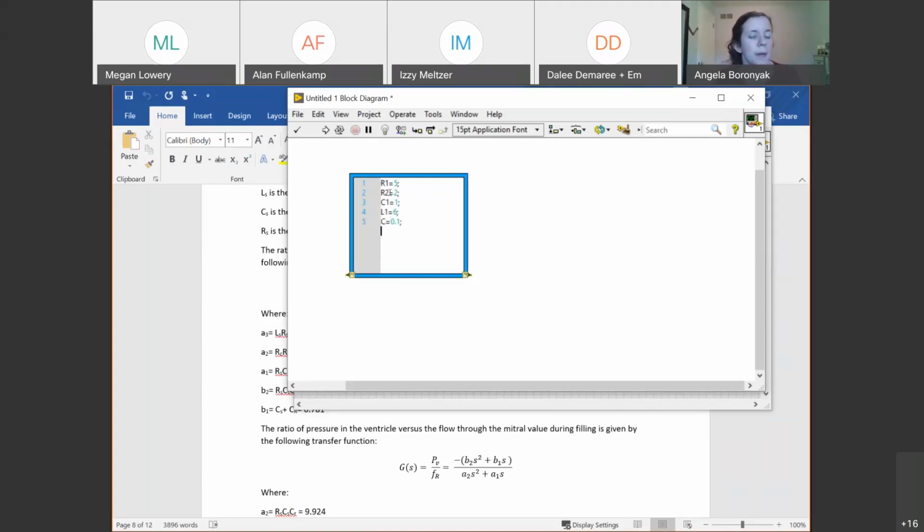Okay. In MATLAB, instead of again having to use LabVIEW to program this, I can make vectors for the numerator and denominator. I think in your lab handout I call them num and denominator, but I'll call them that here. To make a vector, if you remember MATLAB, you have to open a bracket and then you can type your variables, again, if you define them here.